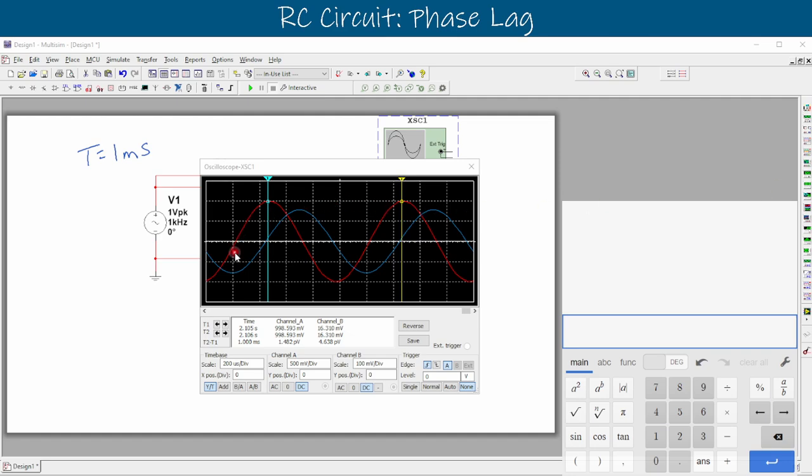are close together. So we see that the red waveform rises and falls, and then that right there is where the blue waveform starts to rise. So we want to compare these 2 peaks here. To do that, we want to compare them on that white line, because that's going to give us the most accurate reading due to sampling of our oscilloscope.